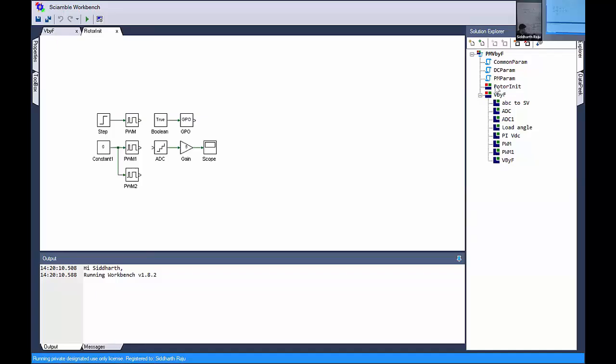Perfect. So initially we don't know where the rotor angle is because this encoder that I have doesn't provide absolute theta. Every time it rotates, it will provide a pulse. So if you count the number of pulses, you can tell the speed at which it's rotating, right? But it doesn't tell you exactly what the initial angle is. But I need to know the initial location of the stator current space vector so that I can figure out where the rotor position is compared to the stator.